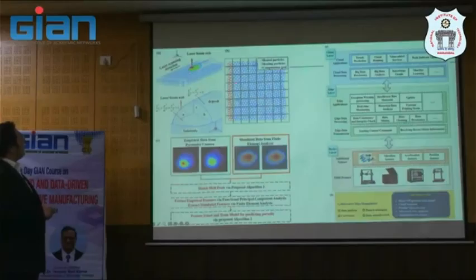And then you use some powder property, some way, somehow you treat in your computational grid. Here, there's some material actually heating, some material actually already heated. And then you will try to predict something that you can use a pyrometer camera to detect, the melt pool size, and then compare again with the simulated data from finite element analysis.